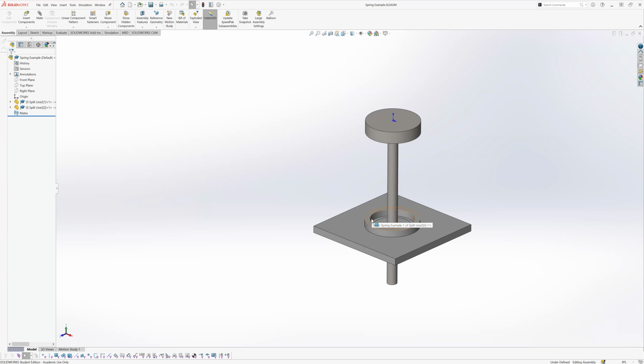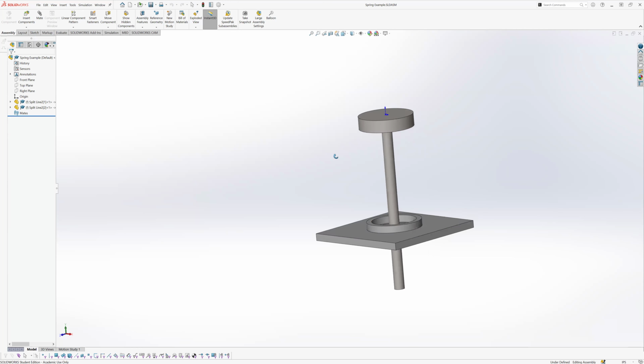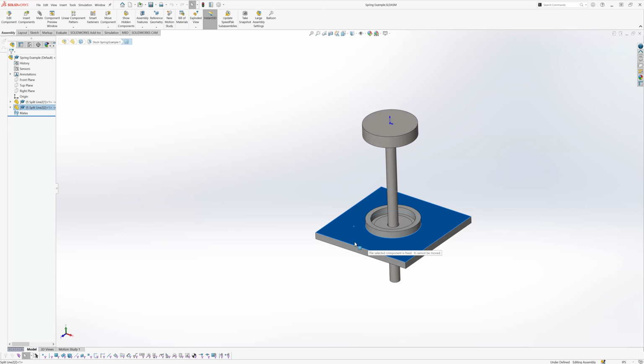Like, obviously, I know that I want these to be the same diameter. It's quick to do those in the part environment and then convert them over into an assembly to be able to have that motion that you get in an assembly. Now, obviously in assembly, if I try to click and drag here, both of these come in automatically fixed. And in this case, I want to keep the base. Just keep the base fixed.